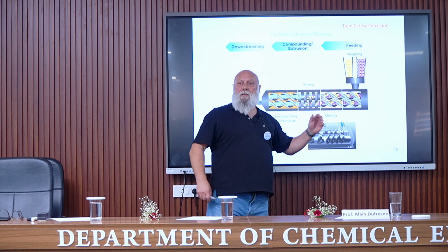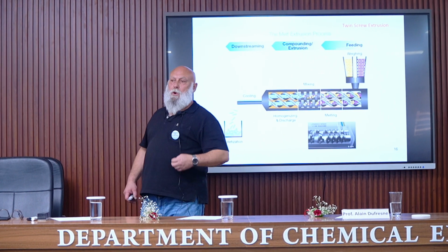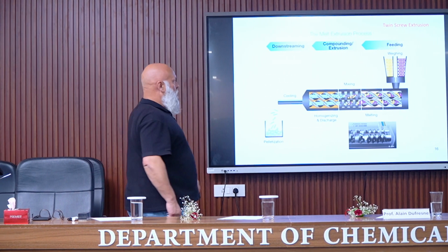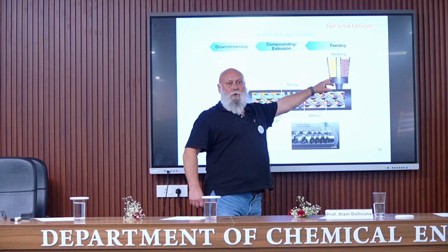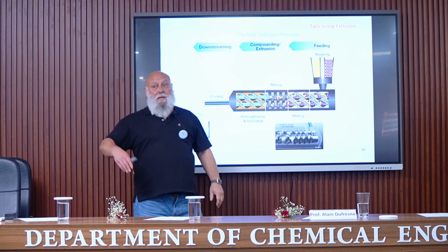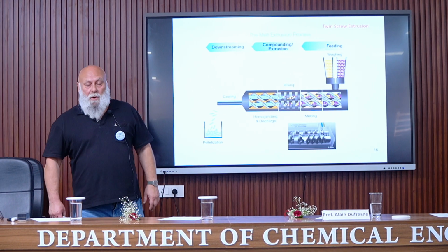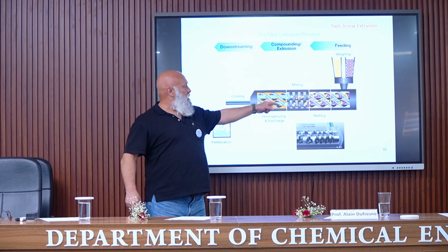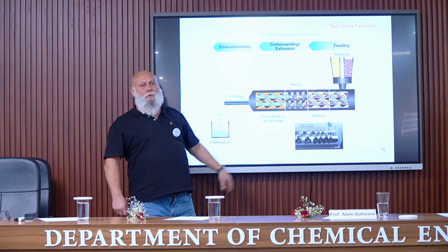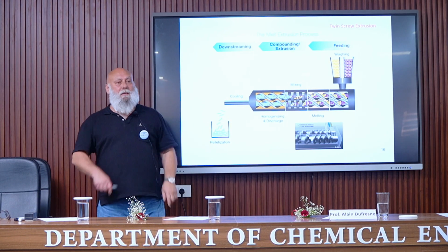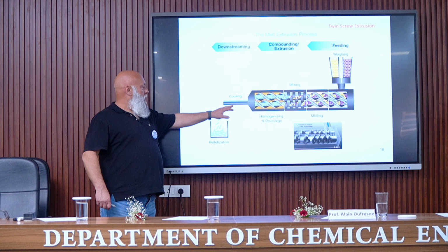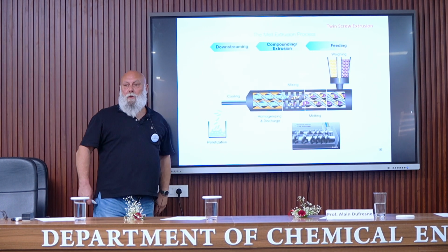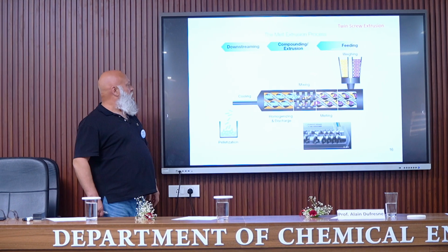So it means that polymer granules are used with different additives that can be, for example, natural fibers. And both materials are extruded at the same time. And a twin screw extruder is used to facilitate the mixing. And at the end, a material is obtained that consists of the blend or mixture of these different components, that can be pelletized and then used for another processing technique.